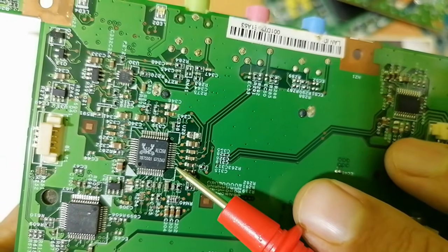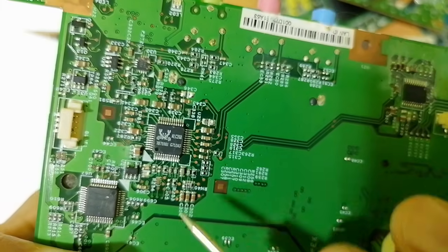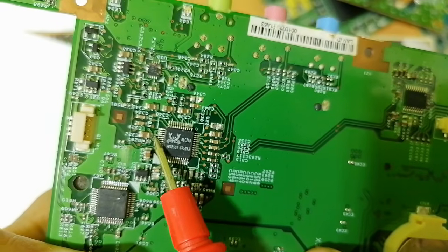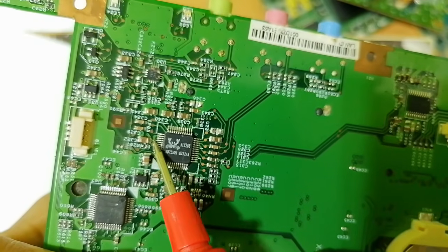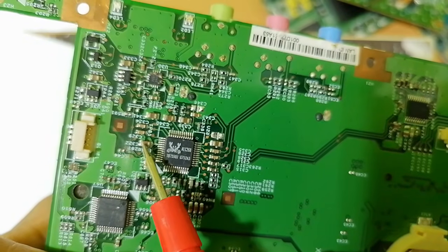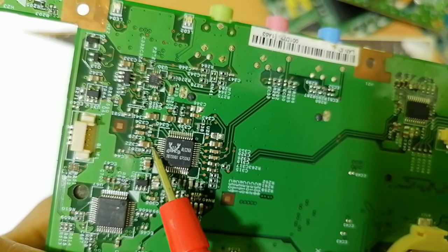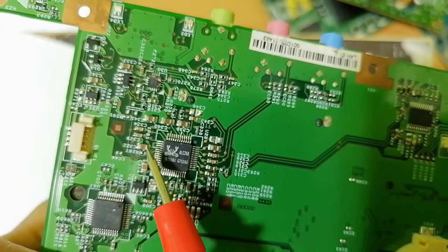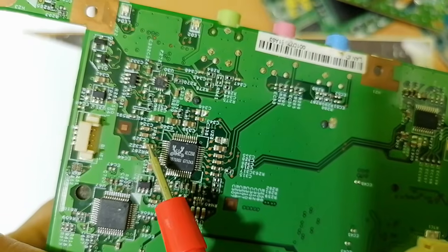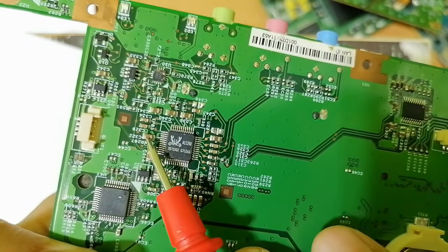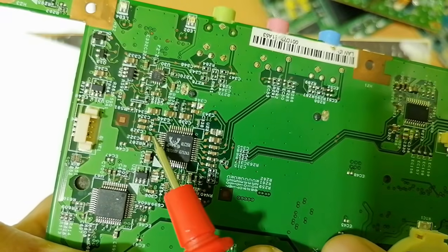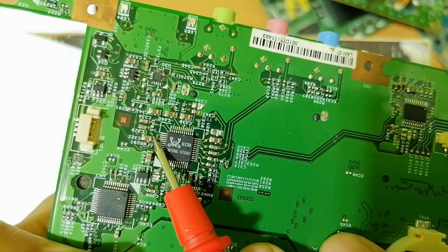That's why, for example, here, let's look for the power where we have the VCC, as you can see. Do you see the bolded line? This bolded line means we have VCC here. The VCC is connected to this ceramic capacitor. Means if you don't find VCC here, you should check this ceramic capacitor. Is it good or not? Because this is the capacitor that feeds this IC with the VCC or the input voltage.